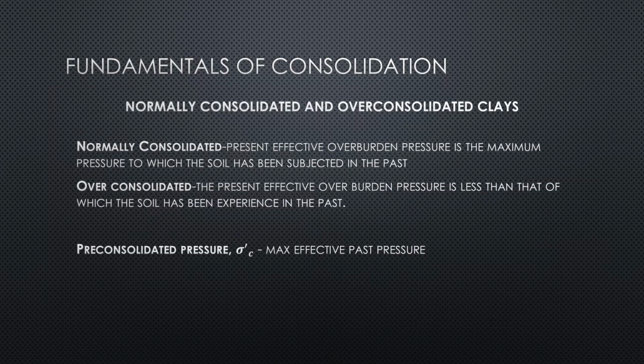Okay. Normally consolidated and over-consolidated clays. What are these? When we say normally consolidated clay, the present effective overburden pressure is the maximum pressure to which the soil has been subjected in the past.